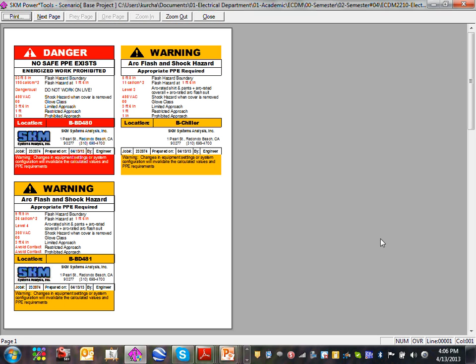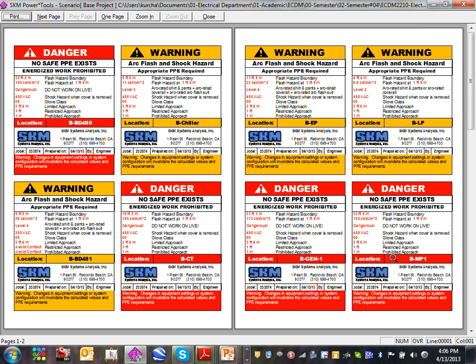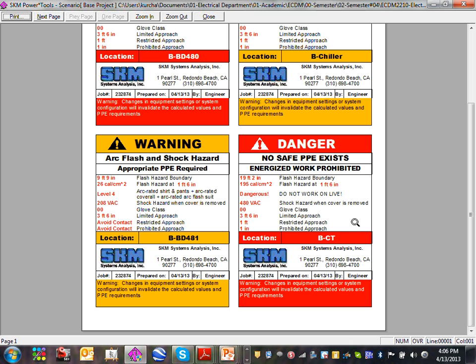Here's another one here, the CT cabinet. Remember how you bring the 4,000 amp conductors into a CT cabinet? Where's the overcurrent protection device that protects it? None. On the primary of the transformer, maybe, or on the secondary, oversized. Look at this. It says if you were to open this one and work on it energized, you're on your own. That's a CT cabinet.